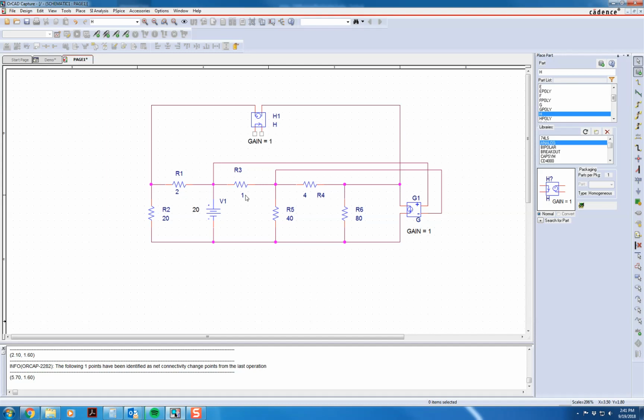and then I'm going to come down to that node. So that's where the current is going to start, and then I have to connect the other end up into the resistor. Now, as a side note, this is actually how you would have to measure current as well, by first breaking the circuit if you're using a DMM to directly measure current. Voltage you can measure with a DMM without breaking the circuit because you're always measuring it across a device.